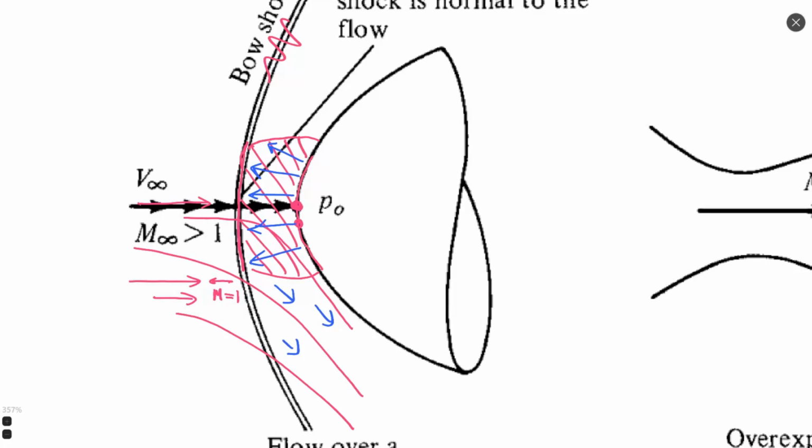Theory of aerodynamics and gas dynamics does not tell anything about such a short transition, because as I told you, we cannot see this as a flow, as a continuous medium. This is why it's recommended to analyze parameters before, after, and see the shape. But do not touch anything inside the shock wave.